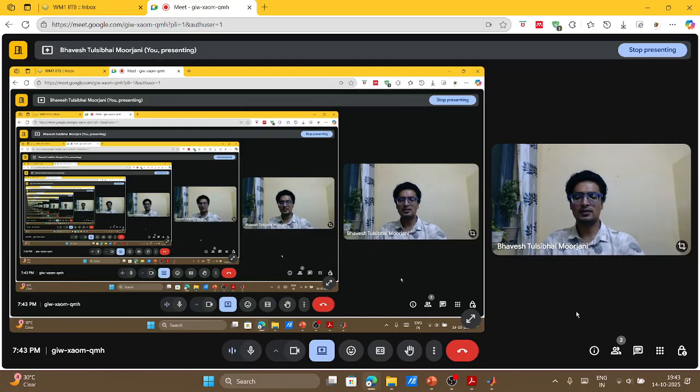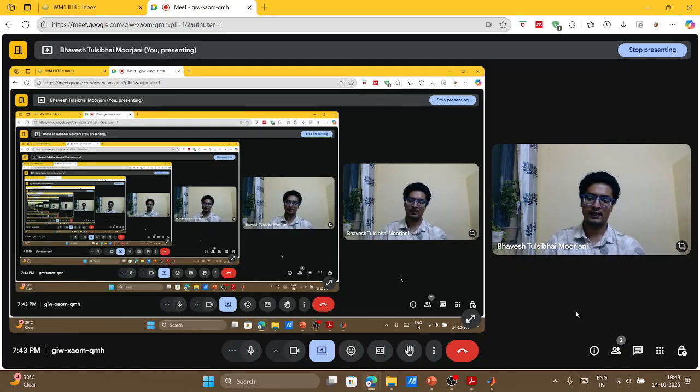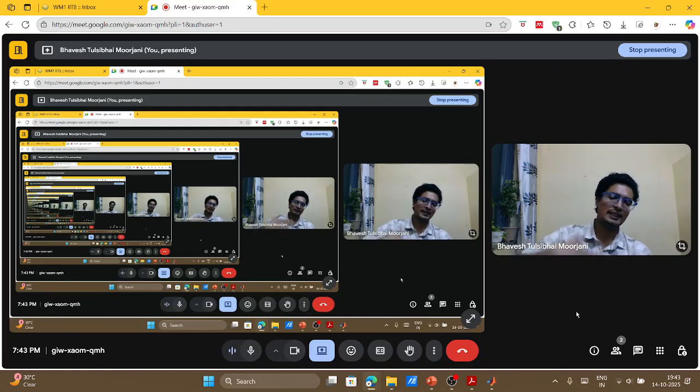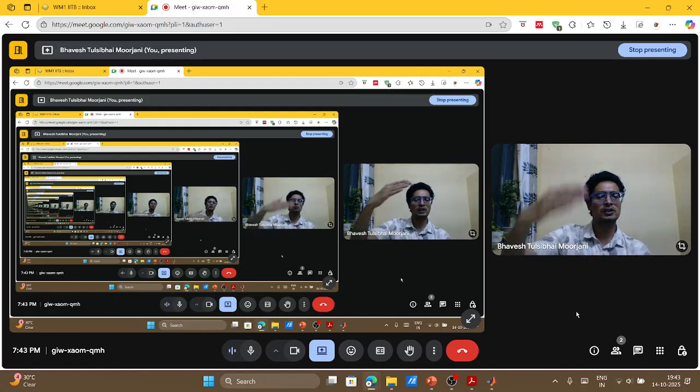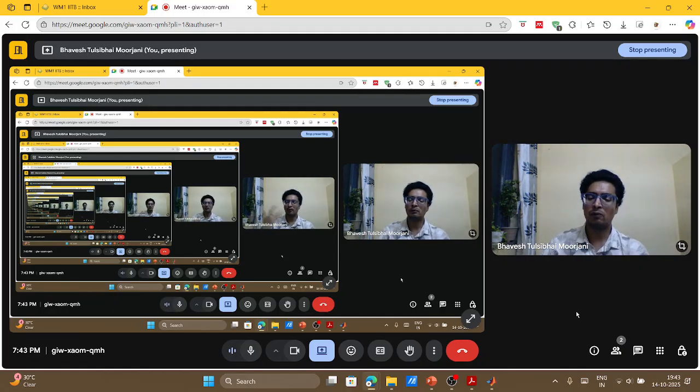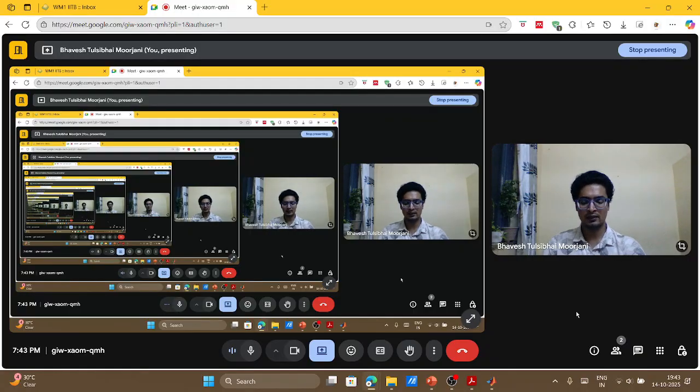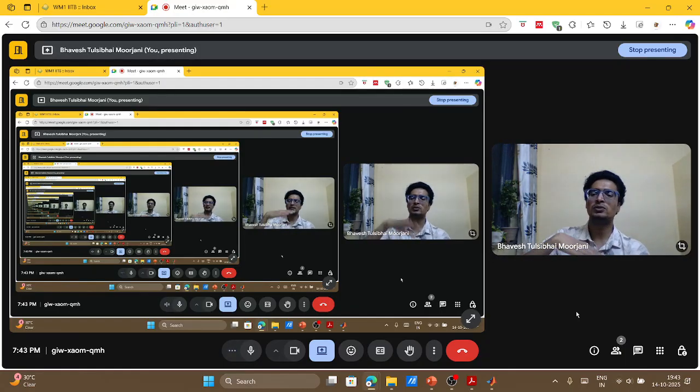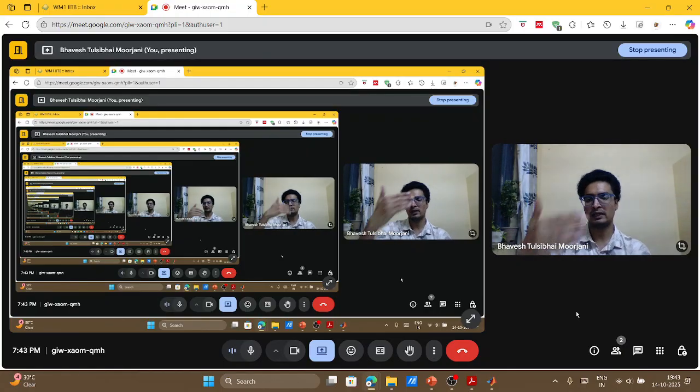So we are varying the TC value to see up to what point we can go, up to what point we can change the coolant temperature in my PFR reactor, right? So that is nothing but a kind of optimization that we are doing, that okay, maximum I can go to this point, after which my product will degrade, right?